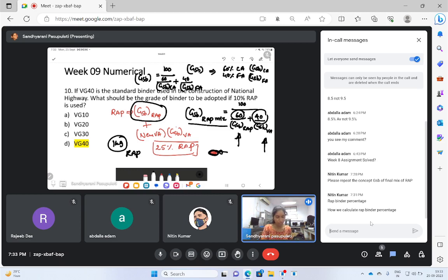So out of this 1 kg of RAP aggregate, finally you will get some amount of bitumen, and that binder is expressed as a percentage of the total initial RAP weight. We call it the binder percentage in the RAP aggregate. We can also use ignition and other methods, but most predominantly used was the extraction and recovery method.